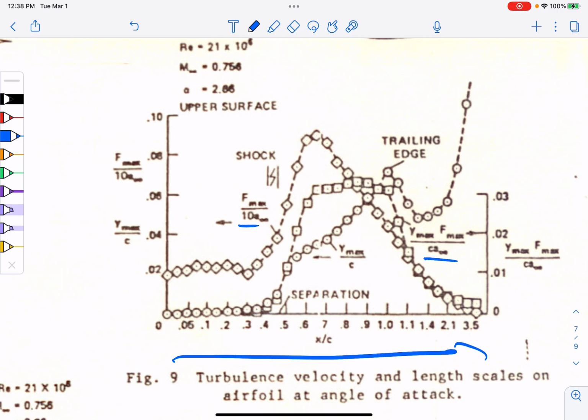And that's one of the beauties of CFD, is you have all the data. And since you know the equations you solved, you can reevaluate terms in the equations and try and match up with experiment. This took an incredible amount of work, and part of the reason he did this is because all these quantities were found from the flow solution itself and not estimated before you started your flow solver, like Cebeci-Smith. And it agreed with the experimental data for a transonic airfoil. So that was a huge accomplishment.